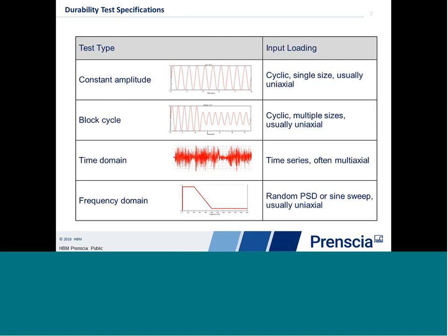This is often used for smaller parts that are inertially loaded, because in this type of test with an electrodynamic shaker, the stresses are going to build up in our device on test solely because it's fighting against its own inertia.